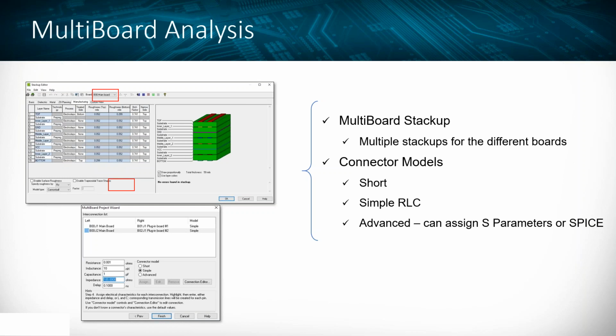So it is very easy to bring in all that information. You don't have to set that up by hand. In the stackup editor in the top left, we can do some what-if analysis, play around with the different dielectric constants that you might be working with, or thicknesses that you might need to adjust. And you can work with your manufacturer in order to get those values as close as possible to what they're using.